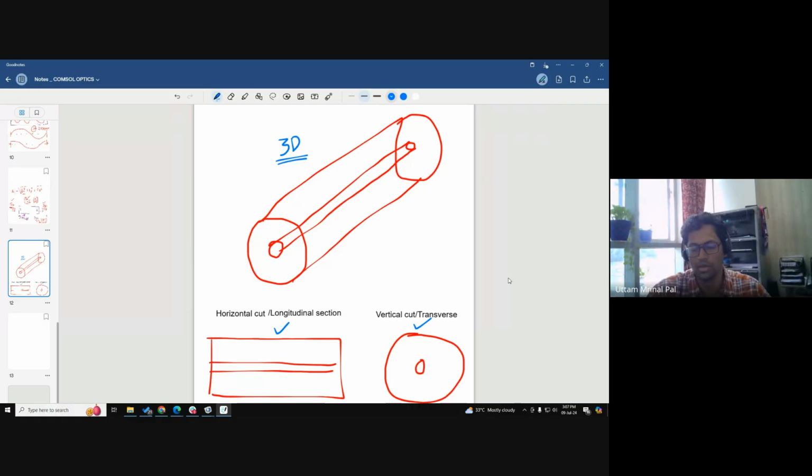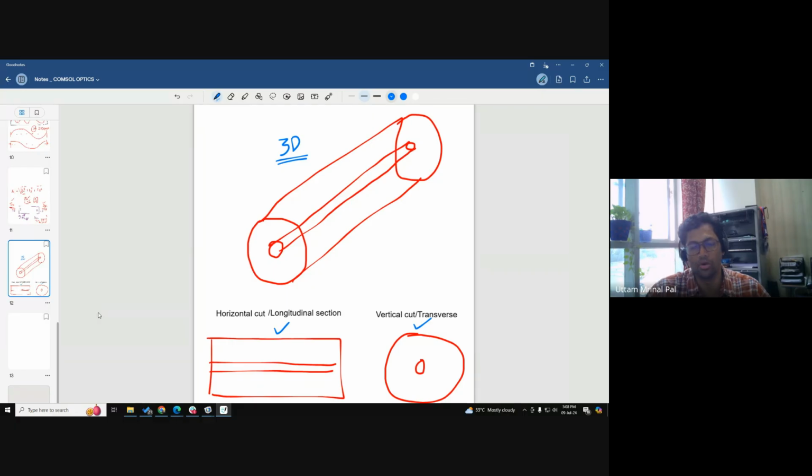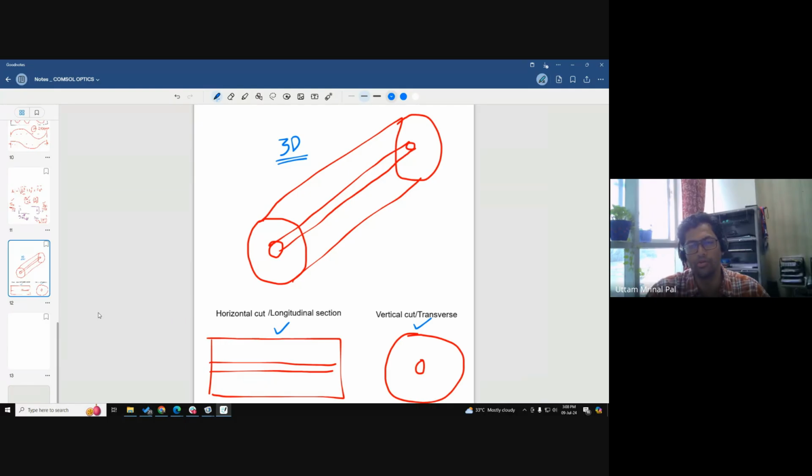That's an excellent question. The first thing is that, as you said, you are working with PCB, so you are working in the megahertz or gigahertz range. That is not a problem. You can still go for 3D modeling. Many PCB models are available in COMSOL. It will still be computationally expensive, but it's not going to be that challenging. The issue with optics is that we are working with hundreds of terahertz, like 200 or 300 terahertz frequency, which results in nanometer scale wavelengths. In the case of PCB, the wavelengths are on the order of meters. So that answers a part of your question.